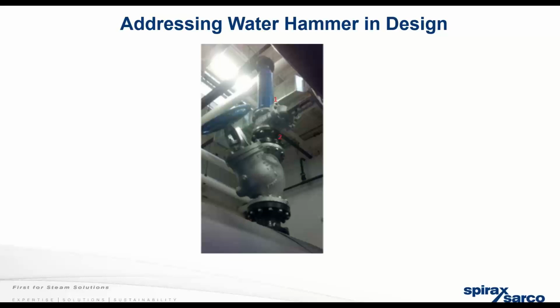So one of the things that I talked a little bit about is designing our steam systems with the valves closed and/or leaking. So this is the typical top of a boiler. You have a stop check valve and an isolation valve, and there's nothing in between the two. And in the boiler case, we could have steam on the backside of this, but we really need to picture getting rid of this water at all times, whether that's a drip trap between these two valves or moving the valves. We just have to think about that and visualize water in our system developing while our valves are closed. Yeah, hopefully that's clear.